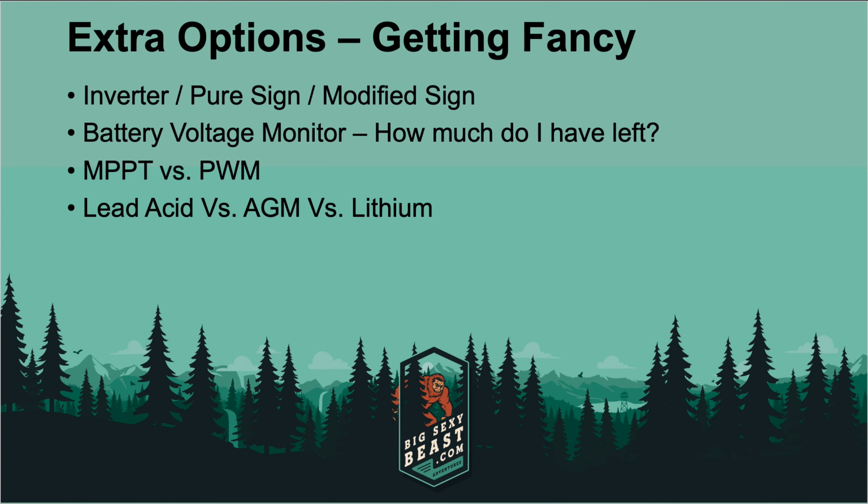I will say that I've got some lead acid batteries in solar applications that I have really, really good luck with. And lead acid is relatively cheap. 100 amp hours is about $100, and you can abuse the heck out of it. And you know what? If the battery goes bad, you go buy another $100 battery, as opposed to buying a $1,000 lithium-ion battery. But if weight is a consideration, lithium-ion is significantly lighter for the same capacity. So something to think about.